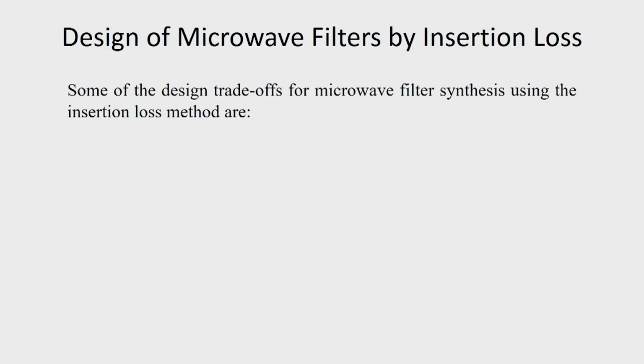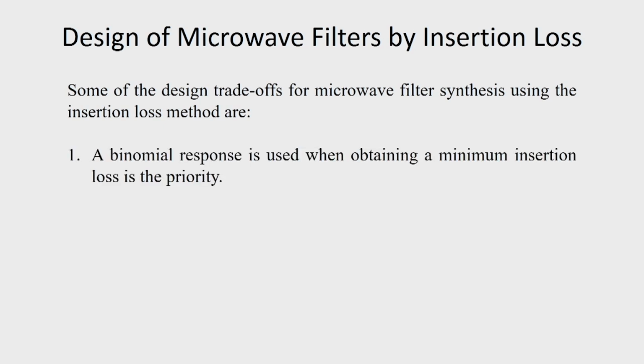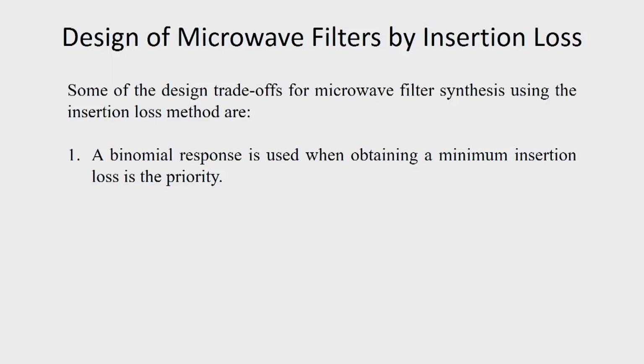Some of the design trade-offs for microwave filter synthesis using the insertion loss method are: a binomial response is used when obtaining a minimum insertion loss is the priority. So, we go for a binomial response when we would like to have minimum insertion loss.